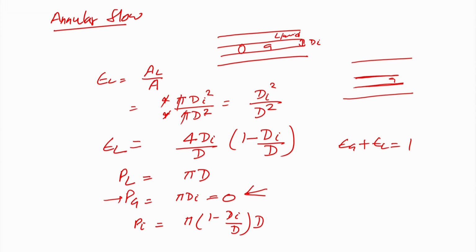If it is a vertical pipe, the gravity term will be there. If the flow is fully developed, you can neglect the acceleration term. So, for any kind of flow, with small or valid assumptions, you can calculate the dP by dx for a one dimensional model. All these models are one dimensional, for which you can get the analytical solution very easily.